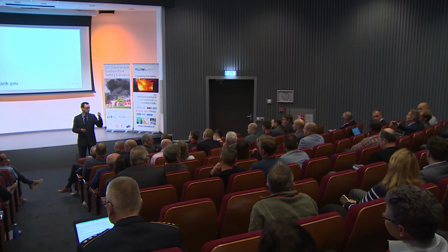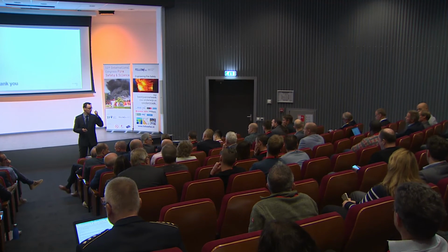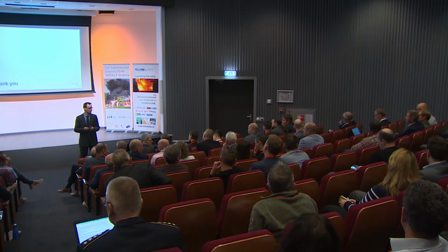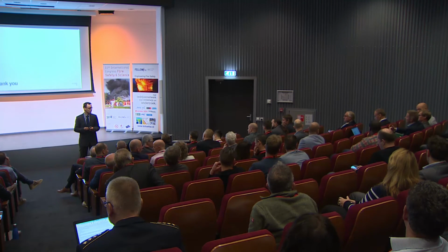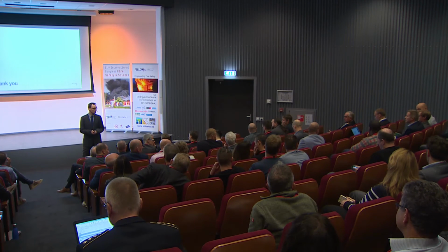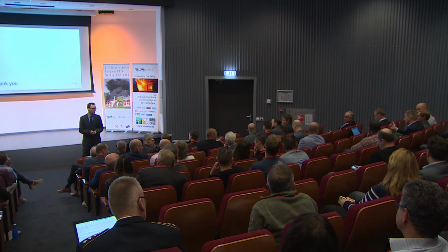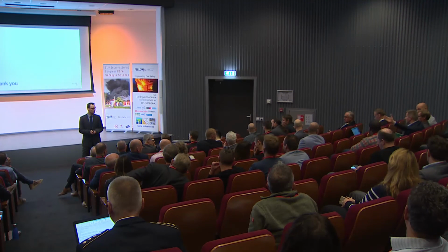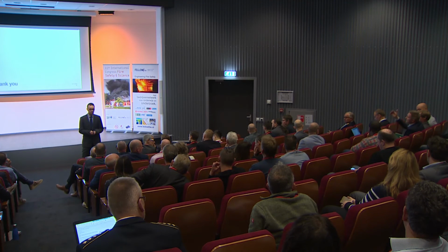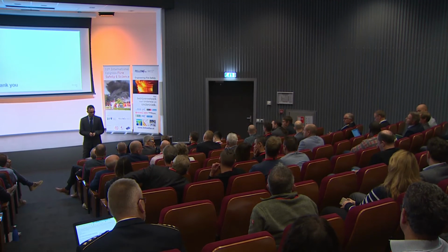In order to reach maximum values of overpressure and so on. So we have seen that the overpressure, even with small fires, is 50, 60 Pascal or something, and at the moment that the sprinkler activated, you have the same behavior as the burnout of the fire, meaning that it drops immediately and it gives an underpressure.